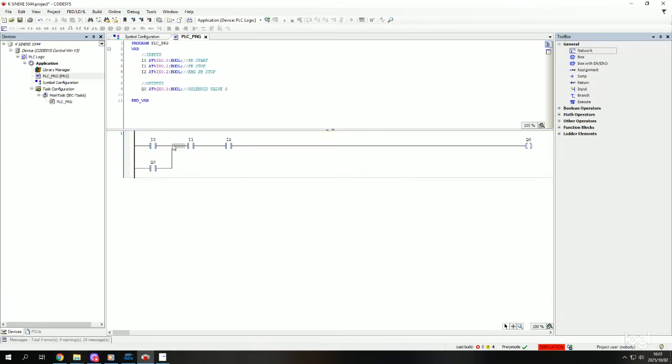So why are we doing this? We are separating this ladder logic diagram into two processes. This loop that we've created, we're basically saying this part of the diagram focuses on advancing the piston rod. That part of the diagram focuses on retracting the piston rod. What components do we use to advance the piston rod? We use a push button, which is presented as I0. What do we use to retract? We use our stop push button and our emergency stop, hence it's on the other side of our ladder logic diagram.